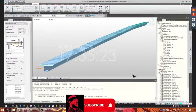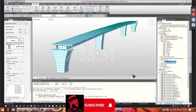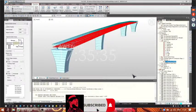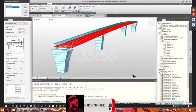The slab is modeled with a plate element. Okay, so you can see the wall structure. This is the slab, a plate element, and this is done for a more accurate distribution of applied loads on it. For this reason, in this case, the moving load optimization has been done with a traffic surface lane. Okay, this is already done.